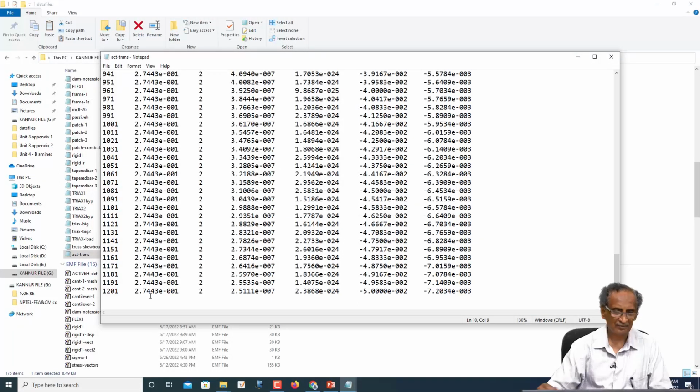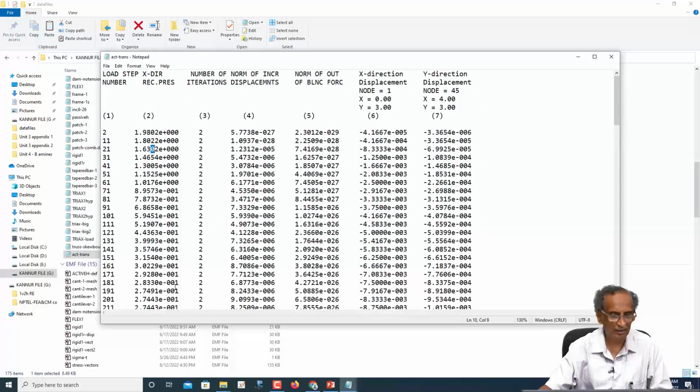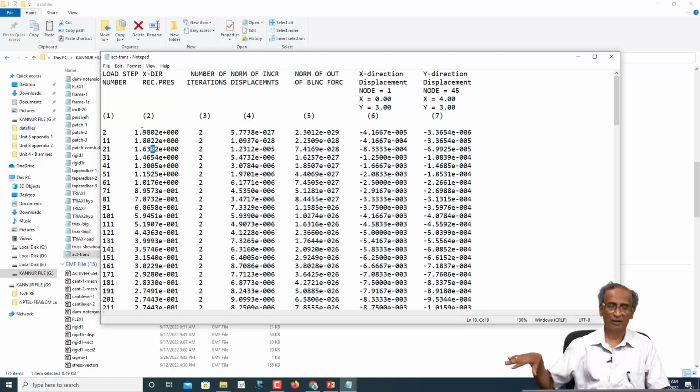And for a friction angle of 35 degrees, the K should be 0.2714. So if you deform a little more, we might reach the limit state, active limit state. But in this particular case, because the K0 is very high, you require very large deformation.